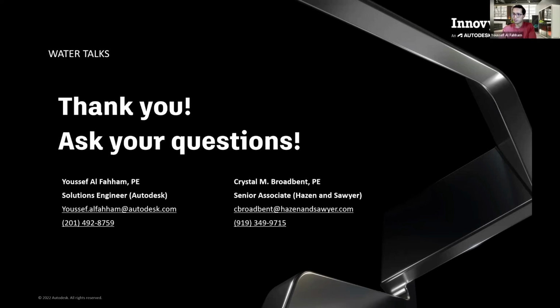Yeah, and there was another question on the whole thing that we just talked about. It looks as though InfoSurge can run within an unskeletonized model. Is this true? Yes. As long as, again, a couple of things I made note of, you can't have negative pressures. What I've seen with some of our models is if you have systems that have a lot of wells, oftentimes we're okay in a hydraulic model knowing it's going to be negative pressure, but you have to change the way your nodes are, either change elevations or whatever, not to change the hydraulics of it, just to get rid of the negative pressures, where you might have them on the suction side of things, because the model won't work.